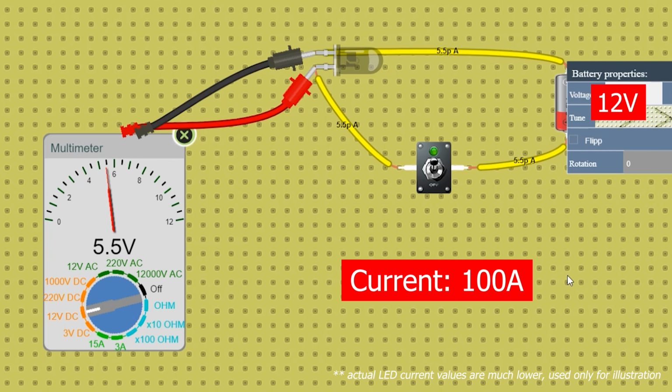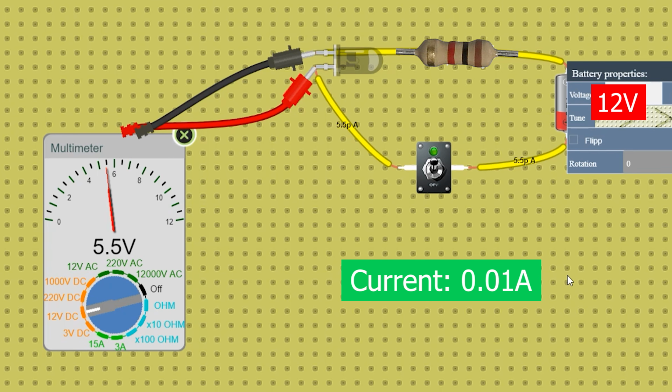So, to power an LED, we need to use a step-down circuit which will keep the current strength within the LED's specified rating. And the easiest way to do it is to use a resistor, which will limit current and allow excess voltage to drop.